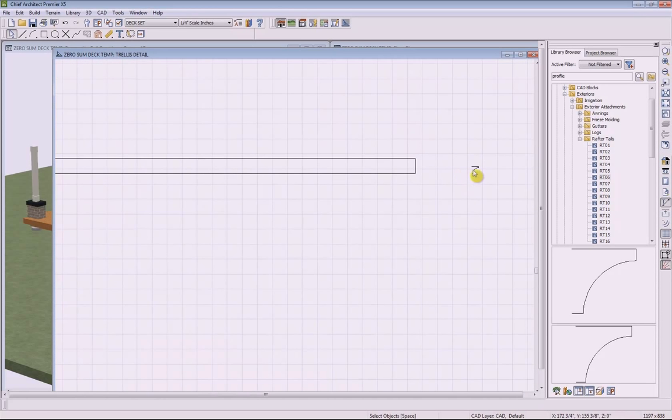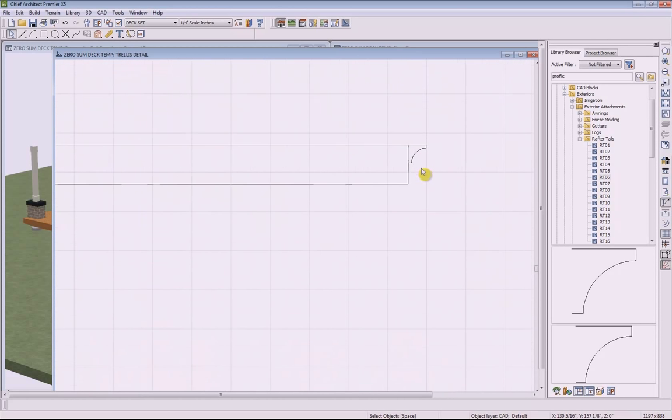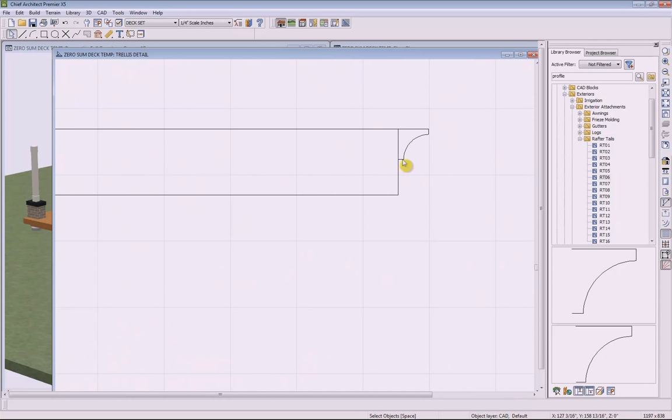We can change that. I'm going to select that molding profile, and we're going to close that polyline because that edge over here wasn't closed, it just had an open profile end. And I'm going to grab that, select it, and do a point-to-point move so that we can easily and accurately move that over to that corner. Okay, and we'll zoom in a little bit further, and I'm going to grab that edge right here, and we're just going to pull that right down and snap that right into place. So that looks exactly what I was after.